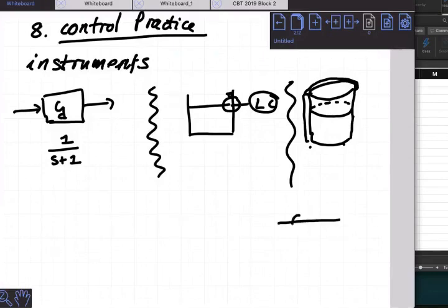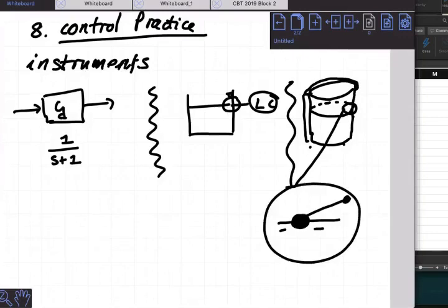Let's say we could maybe use something like a ball float that's in your cistern in your toilet to measure this level. So if we zoomed in on that corner over there, we could say, well, there's a liquid level, and on the side of that vessel there's an arm that's physically, mechanically connected, floating on top of that liquid level. And that's the one place that I want you to go to when we think about this larger scale of control practice, right? That in reality,